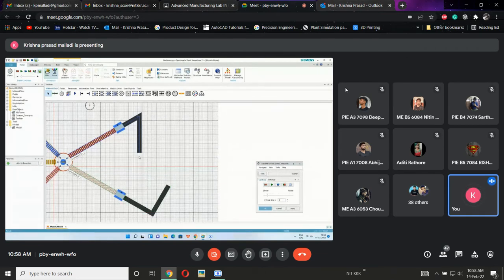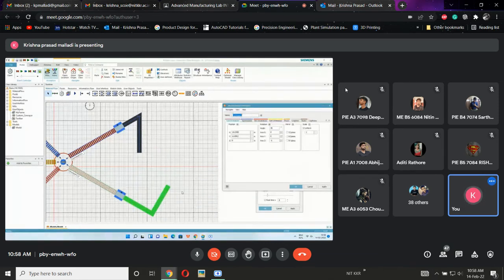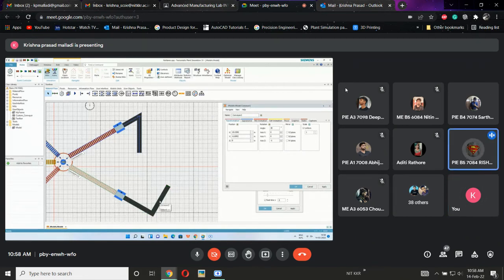Now how to maintain these two? For that, edit 3D properties. What is the angle I should be having for this one? How to make this one parallel to the y axis? So we will change the angle to minus 120. Where exactly do I need to write this minus 120? Segments, and then you have to go to the tangential angle.